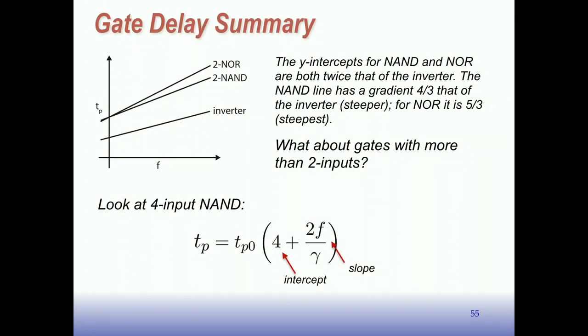So the other thing about high input logic gates is you have long strings of transistors, and that tends to be slow. And so there's another term, kind of an exponential term that comes into this. It's not even linear anymore. And so it gets worse than what I told you here. All right, so we tend to favor logic gates with a relatively small number of inputs.